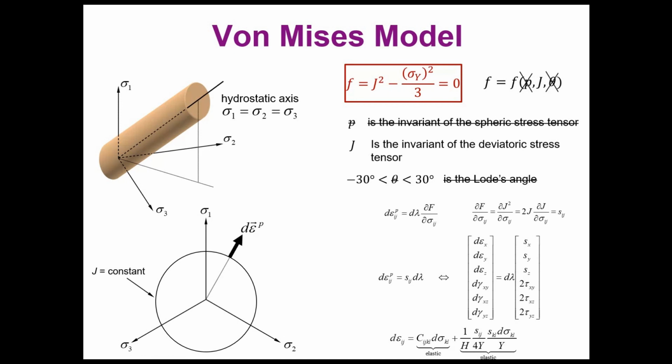Is a parameter that defines the type of plasticity you have. If you have, for example, a bilinear model, this h will be a constant because it's just the slope of the second line of your model. But this y in here, if this is the plastic strength, will be variable depending on the level of the strength.